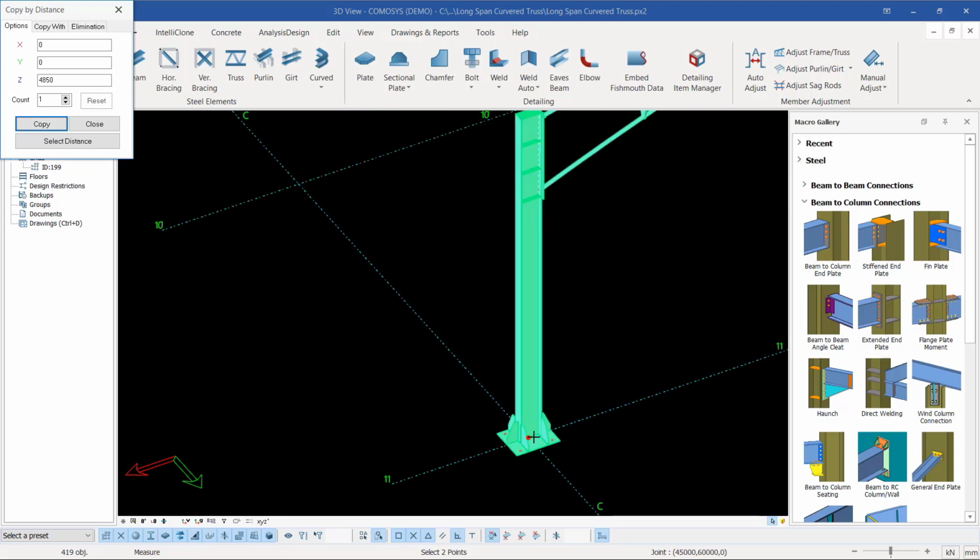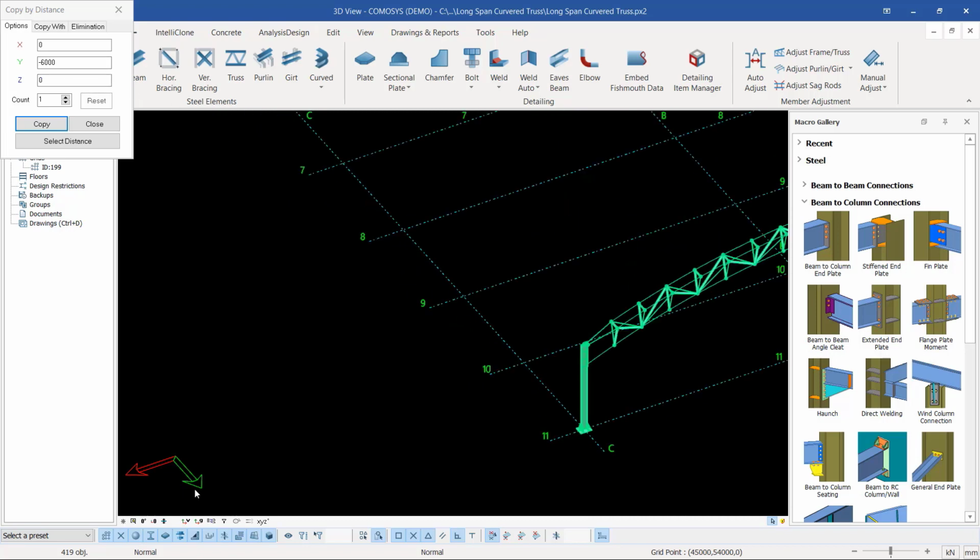Now you can see, as it is now, I want to define my first bay. How long is it? I'll snap on that spot and move all the way to that particular end. And you can see before I click, it is 6,000 millimeter, which is 6 meter. I'll click on that spot. So the moment I click on that spot, you can see on the y-axis we have 6 meter, but that distance has been prefixed by a negative sign because we are moving in the opposite direction of the y-axis.